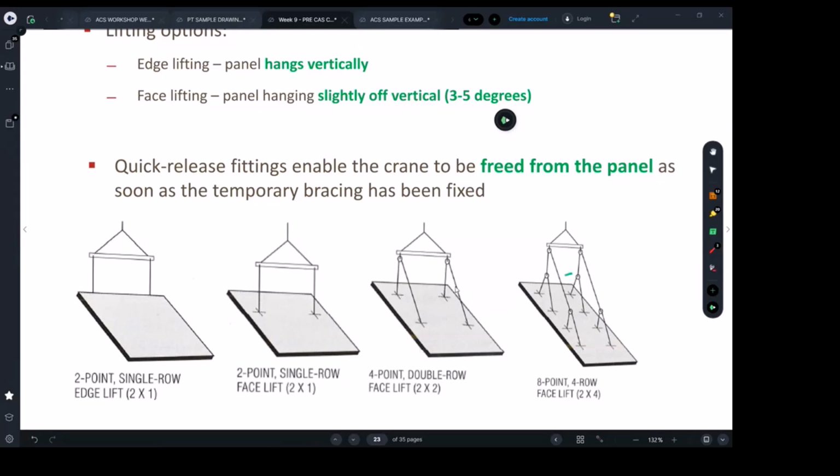If you allow for 4 points, you can cut down the lifting height by half, and that will let you go over the power cable or trees. So that's really the challenge. The structural engineer cannot think about this alone. The architect cannot be thinking about this alone.